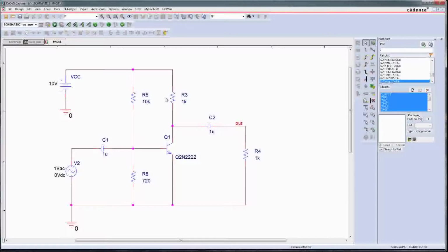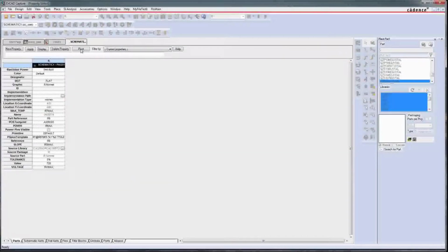Today I'm going to show how you can define and how to calculate the sensitivity of a circuit. I will also explain what it means, and how to calculate the worst case results. For that, I'm going to use this very easy circuit. There is just one component with tolerance, this resistor here, with 5% of tolerance.